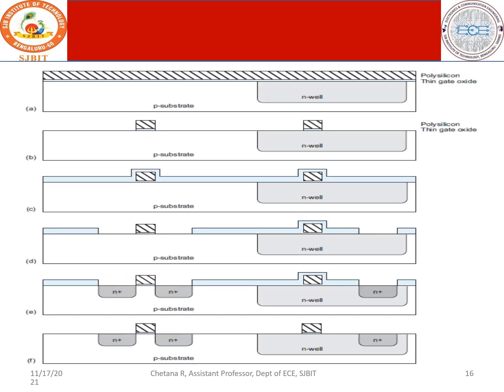You can look into this diagram. So the N well is created, polysilicon is made to deposit on every region. Where it is required, only there we will take care of polysilicon, and where it is not required it will be removed. So you can notice this is your polysilicon, this is your polysilicon, and below that you have an oxide. The oxide here is called thick oxide. Next you are going to form the diffusion on the P substrate. Since it is P substrate, what is the type of diffusion you have to do? N type. This is called self-aligning.